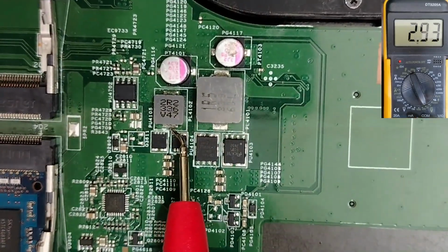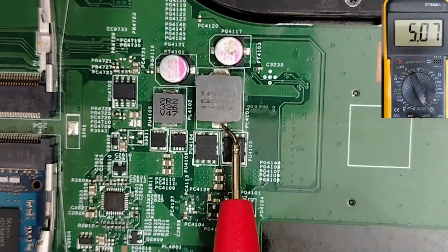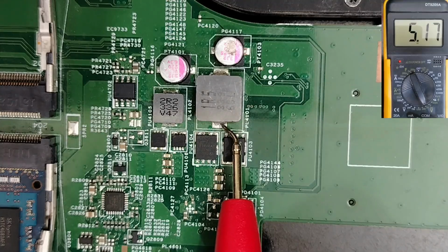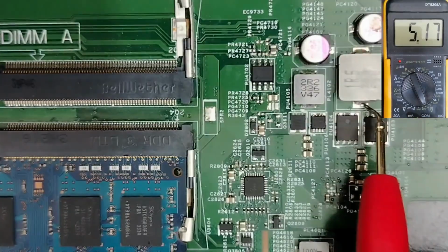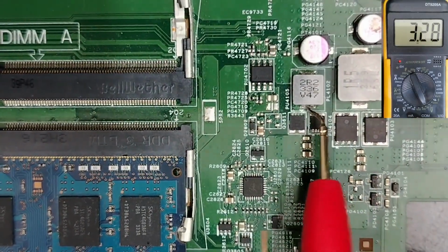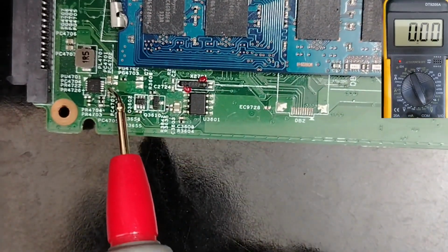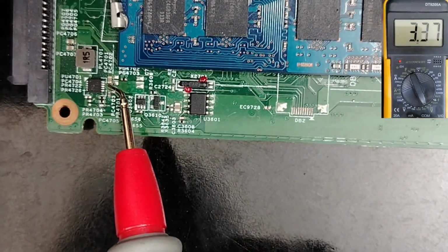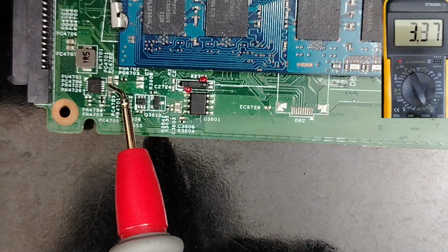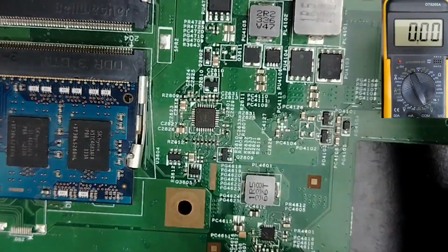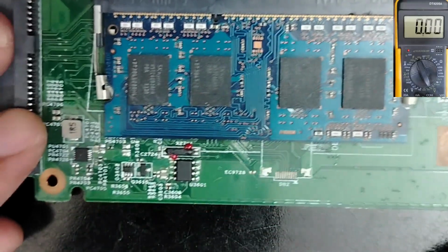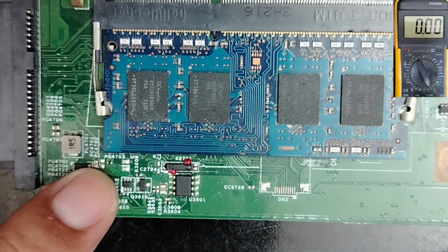That's why, guys, I told you that the 3.3 volt and 5 volt are the most important voltages in every motherboard after the B+. I can even do the same thing and check between this point here, 3.3 volts, and this capacitor here. We have to find a direct connection. Let's do it again. So we have the inductor here. We have the ceramic capacitor here.